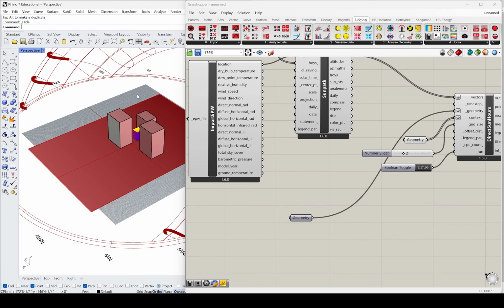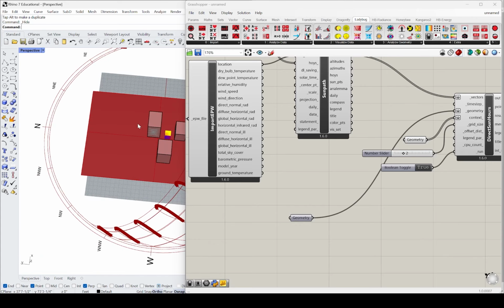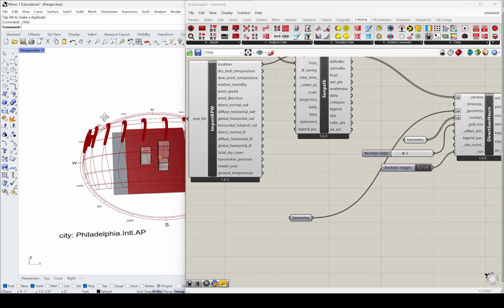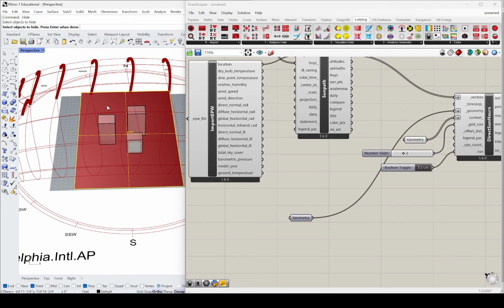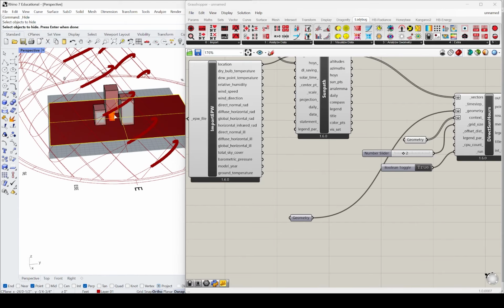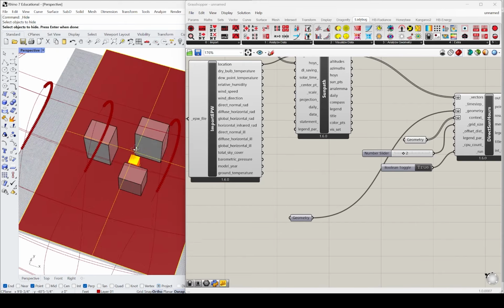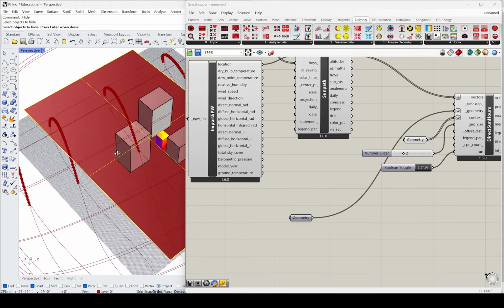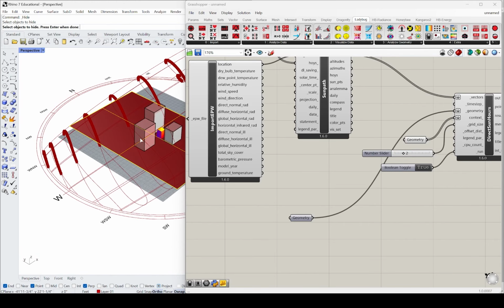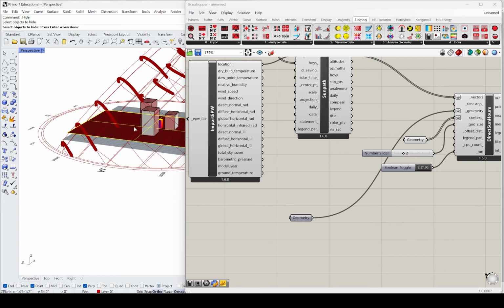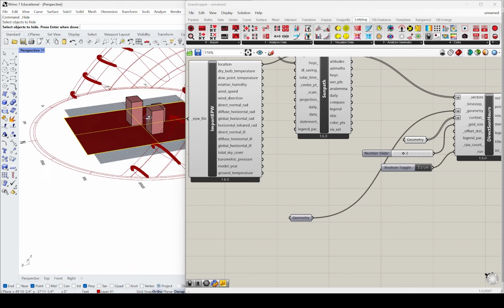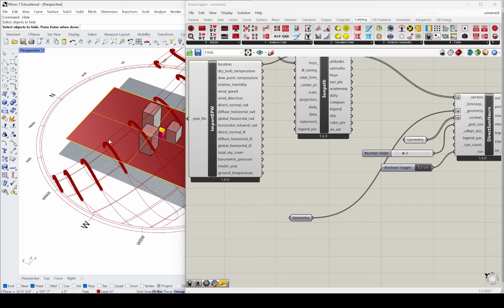This corner's changing, right? Which is what we would probably expect because this is south. So I'm getting morning sun on this face. Sun's coming up. I'm getting a lot of sun on the roof. Sun's coming down. I'm getting maybe a little sun here, but I'm probably starting to get blocked by this building. Yada, yada, yada, right? So that's direct. So did everybody see that?